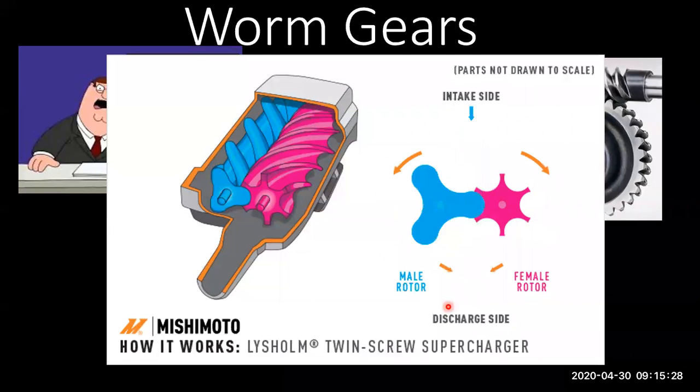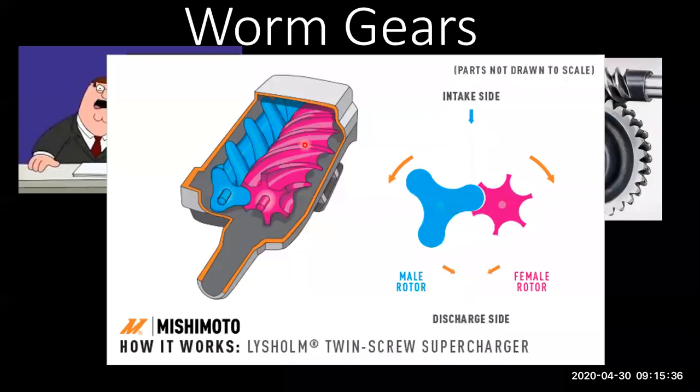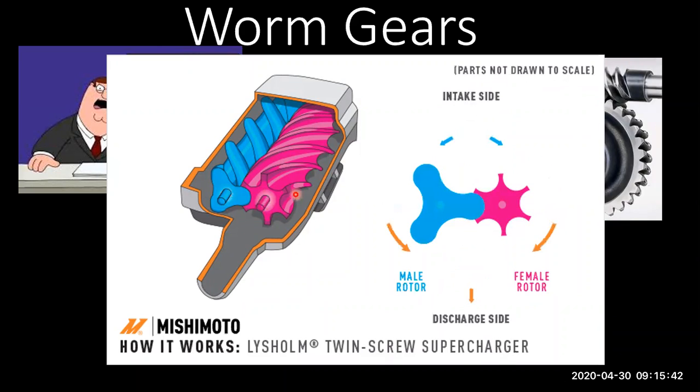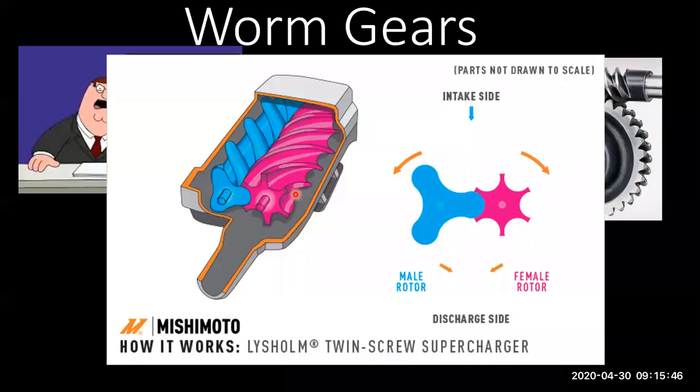So this is another application. So when this moves into the screw, there is no worm wheel here, but we have only the worm. So one such application in motorized application. So here also it is made up of a softer material relatively, like a phosphor bronze, so to dissipate the heat and stuff.